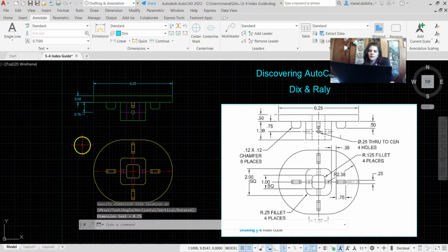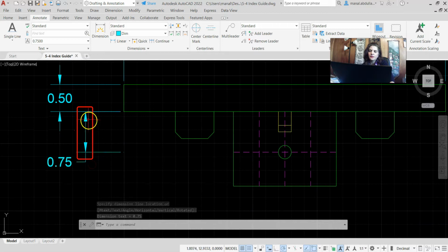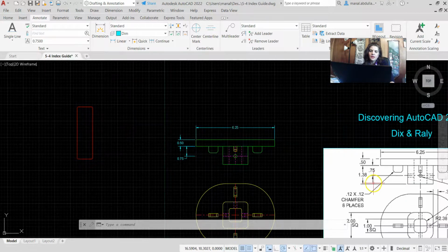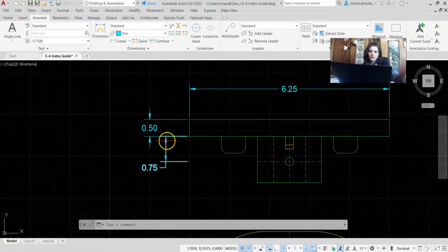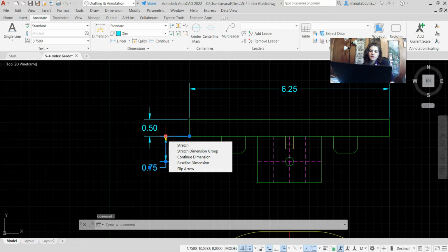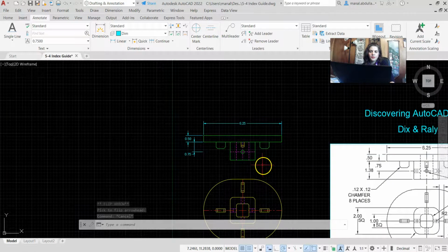We can move it a little bit. Now, I need to mention here, look at that, the arrows are from inside. However, here the arrows are from outside. To do that, you can go to each arrow. Okay, and this is the grip. You click on flip arrow. Similar, flip arrow. So without clicking, actually, you just need to hover over till you see the flip arrow.